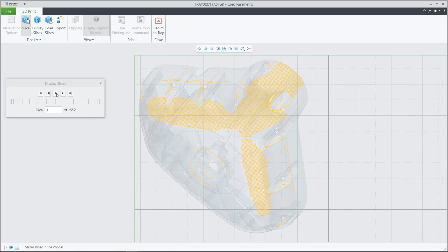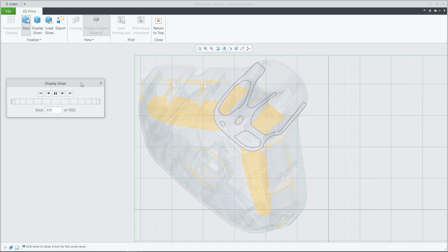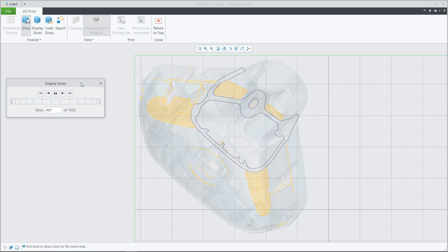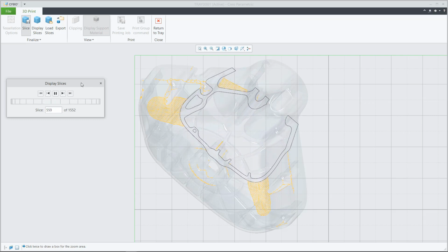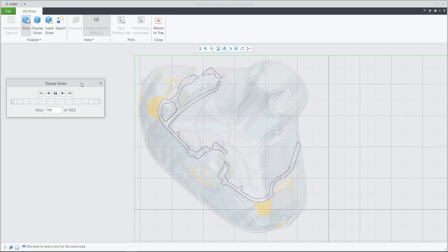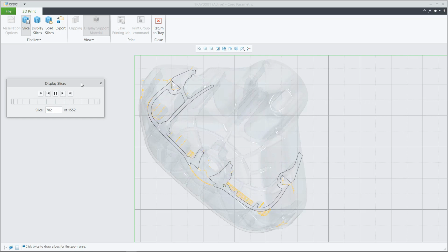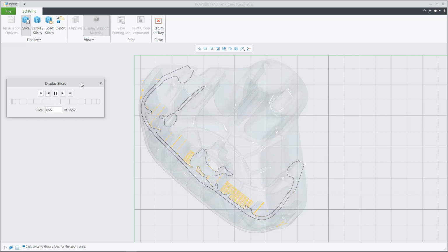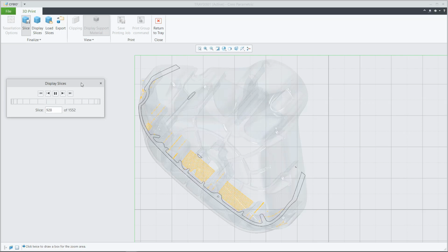And that's really the key here, is to get all this intelligence and work right on the Creo model, the Creo secondary model with all the material removed for secondary machining, and then put it in a tray. We're going to print this out of plastic, out of metal, using this particular machine. Here are the slices that we need to do that. That, along with the lattice capability, is all within our additive manufacturing extensions as part of Creo Parametric.